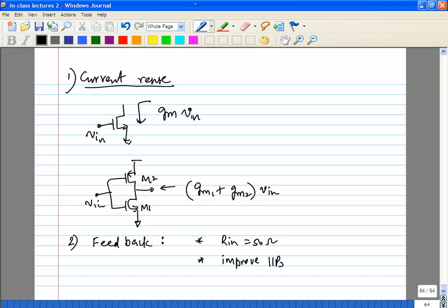But the obvious negatives are that noise figure may increase, that's one big thing, and gain will decrease, so that is another thing. More importantly, the gain decrease will also impact noise figure, and lead to an increase in power. The other thing is stability. Once you give feedback, you need to worry about stability.